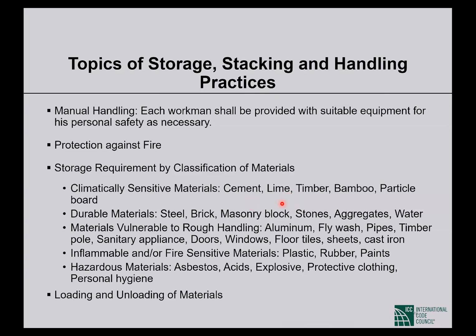For example, steel. Do you know, if you have to preserve steel for a long time, for example, you have already purchased steel, but your construction will start one month later or two months later, what will you do? Your steel will rust. What to do in that case? I think many of you know about this, that you can cover the steel with grout, with a cement water mixture. That will protect your steel from corrosion. So these details are there.